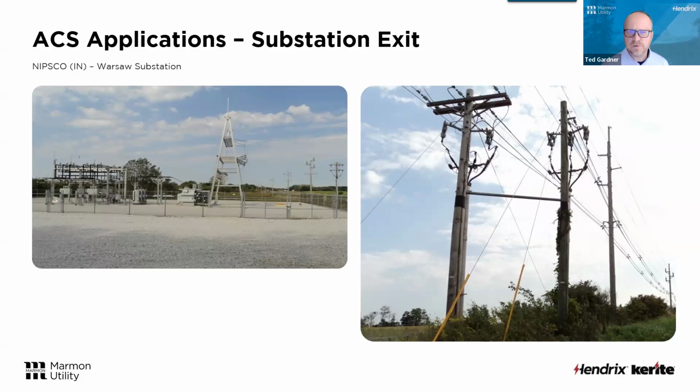Maybe those poles are 300, 350 feet apart, and then we just size up the messenger to do that. So it works really well, and it minimizes the number of poles. I've met in the past with G&T contractors that'll say, if there's any opportunity for there to be distribution underbuild, we purposely have to put our poles a lot closer together. And with spacer cable, we don't have to do that.